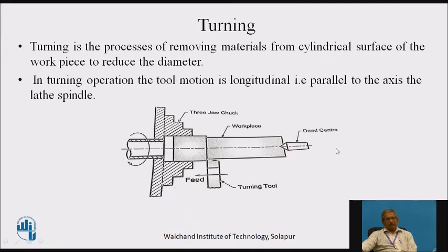In turning, you must keep in mind that the tool travel will always be parallel to the axis of the lathe. So this is called turning. In the operation, the tool motion is longitudinal, that is, parallel to the axis of the lathe spindle.